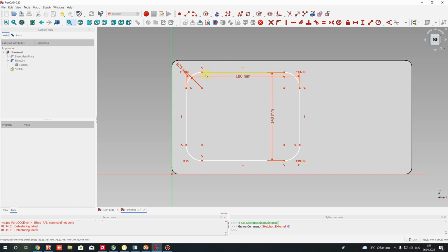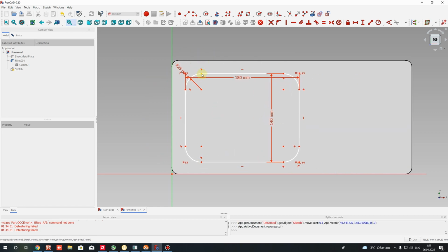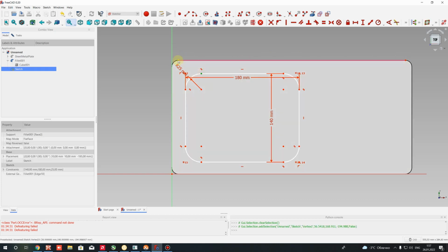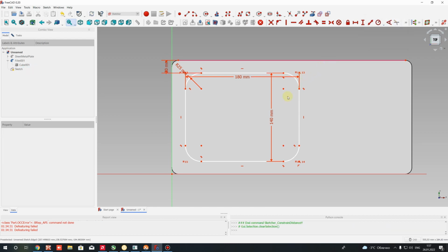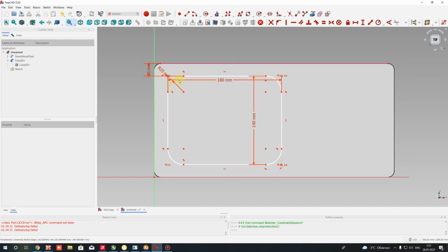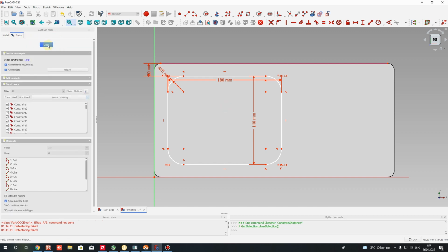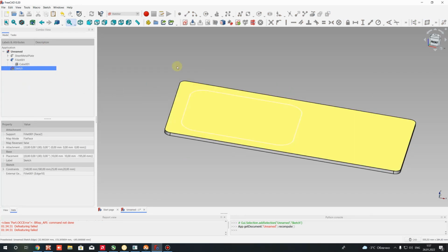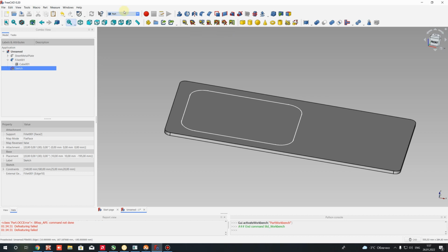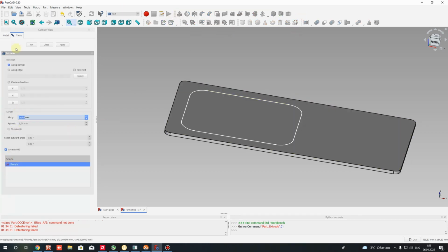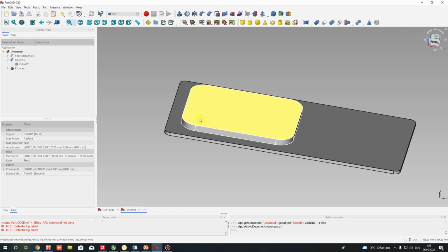Let's position this rectangle on this flat plate. Let's choose this tool, and let's make an edge from our 3D model. Let's import this edge, and we can set the dimension between this edge and this rectangle. Set 20 maybe, and after that, let's close the sketch, go to tasks, close, and for the sketch we will make the extrusion operation in the Part workbench. Let's go to the Part workbench, Extrusion operation, and we will make some extrusion here.